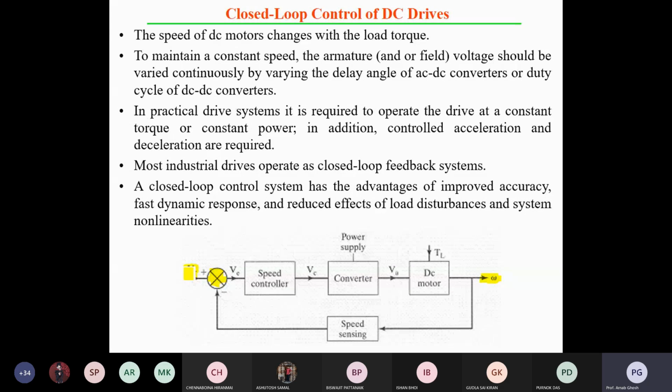The speed coming after the tacho generator, which is a transducer, is converted to a relative, equivalent voltage. If that voltage is sufficient to compare with your reference value, fine. Sometimes the voltage value is less, so you need to amplify it, scaling that voltage up. Otherwise, another option is to convert in such a manner that you get the actual value and can put the equivalent value of the reference voltage.